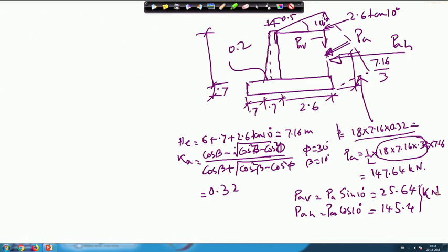Now, in addition to that, what are the other calculations I have to do? For stability analysis, you have to calculate the gravity load. You can see that now I have imagined this is the wall. So, this soil will be there, this concrete will be there. And another thing I have missed, on this side there was an embedment, some height. As I have told you, to be on the safe side, this can be ignored. This side will be passive and this side will be active, and if I ignore the passive pressure, generally we will be on the safe side. So, for the time being I am ignoring it.